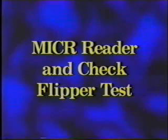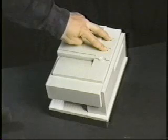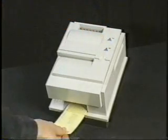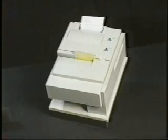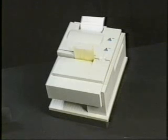the hardware service manual. To run the MICR reader and check flipper test, place the printer in the offline mode. Press and release both buttons again. Insert a test check face down with the MICR characters to the right. The MICR characters will be read and printed on the customer receipt. The check is then flipped over and exits the printer. This test checks all of the operations of a check being franked and printed.